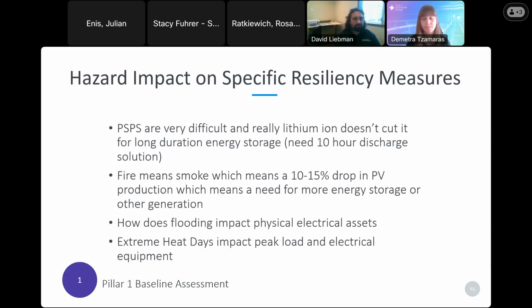So going through this process where we then conduct our load prioritization, as well as our hazard impacts, after we had completed our load prioritizations, we were then able to look at those loads and those buildings and rank them. Followed by that ranking is how we then looked at the load of those buildings in their ranking groups, and we're able to size and then design our solar and battery microgrid.